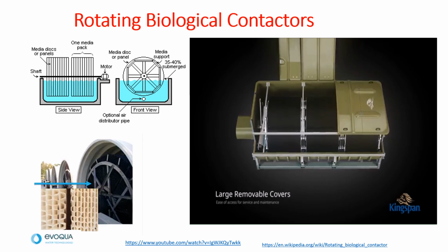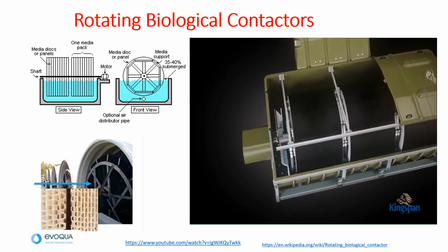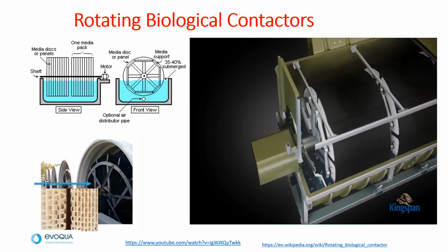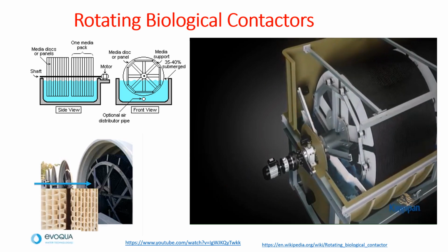And usually these rotating biological contactors are placed in a covered environment to protect the biological process and also to avoid damage by ultraviolet radiations. If you see here, around 35 to 45% of the media is submerged in the wastewater tank.